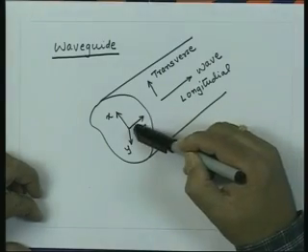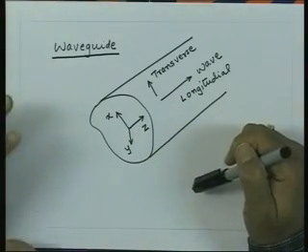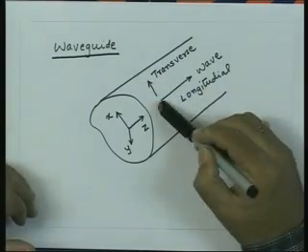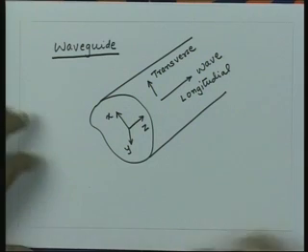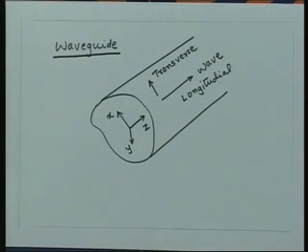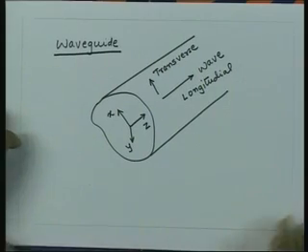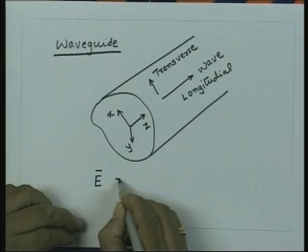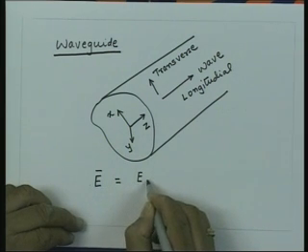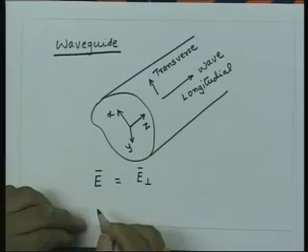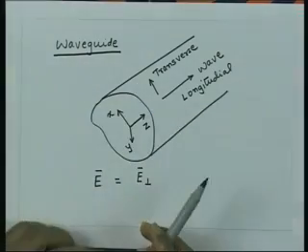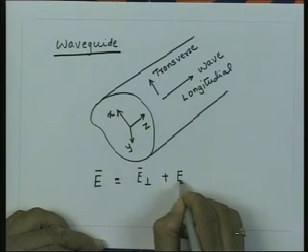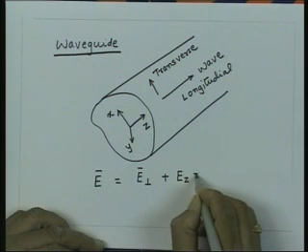Since the longitudinal direction is the same direction as z, essentially any field now has two components, one is the transverse component and the other is the z component. If we do that, then I can now write down the electric and magnetic field in general. So, I have here the electric field, which is a vector. This can be represented by the electric transverse field, which is a vector, because it can lie anywhere in the xy plane, plus a longitudinal component, let us say its value is Ez and it is oriented in the z direction.